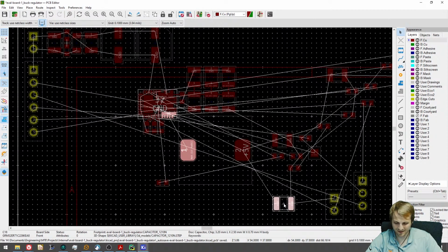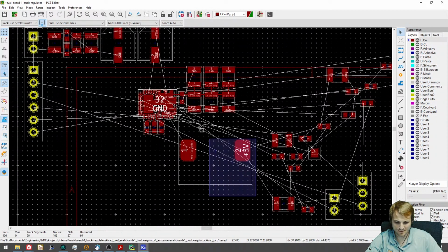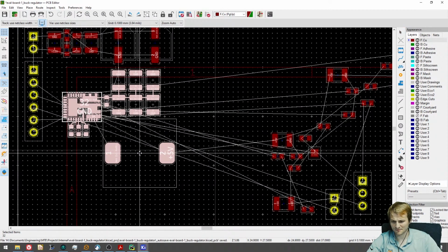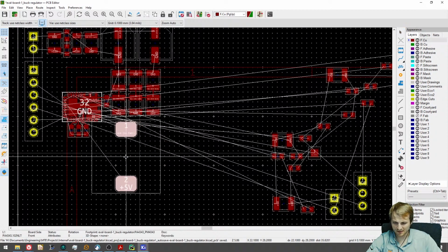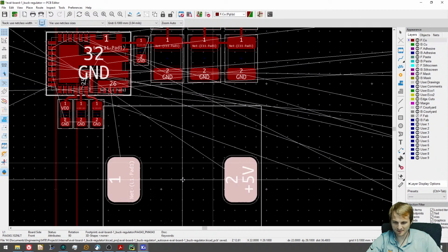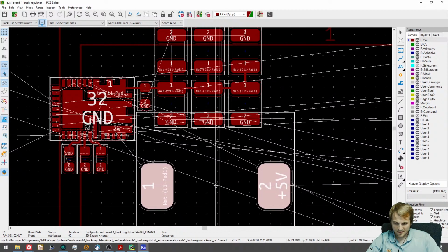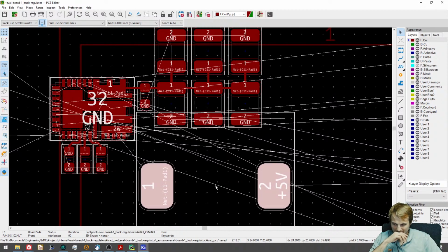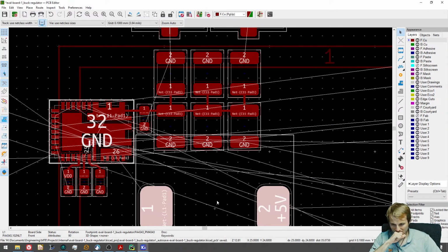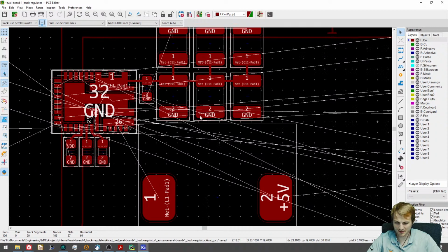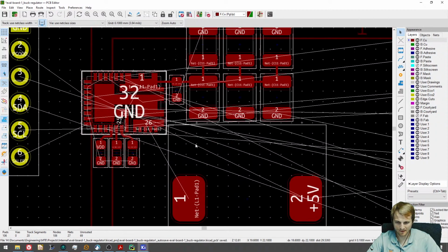Such a big inductor. It's funny because it's only 1 microhenry, but it's like a 20 amp inductor, so it's a beast. This actually might work pretty well, but yeah, we don't have a great option here with just how massive this is. If we could get this up a little bit, let's keep this down here for now and see how it plays out with these later on, because it might make more sense to bump this up a little bit, but we'll see.